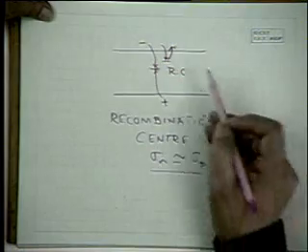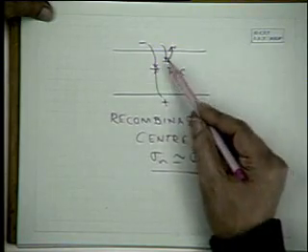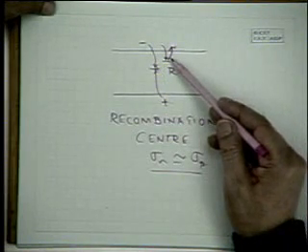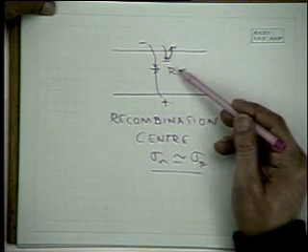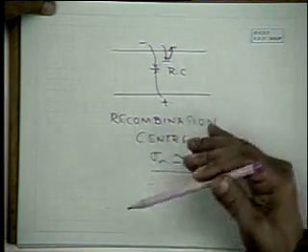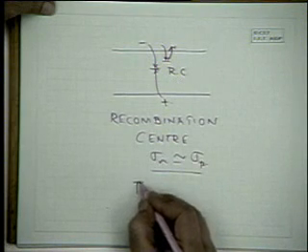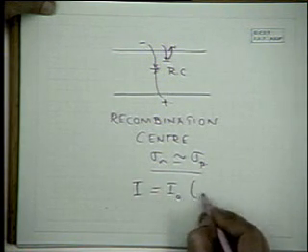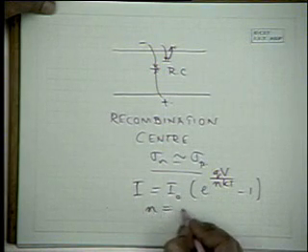Now, in a very good semiconductor, obviously silicon, the concentration of recombination centers is extremely low. Concentration of unknown traps is also very low. You have only intentional donors and acceptors. But if you have a polycrystalline material, or a thin film material, there will be appreciable recombination centers as well as traps. The traps will lower the mobility. Recombination centers will result in an increase of dark current for solar cells or for transistors. The reverse bias current will increase due to recombination centers. And if you look at the IV characteristic for a PN junction, we know that this is given by e to the power qV over nkT minus 1. n is equal to 1 for an ideal semiconductor.